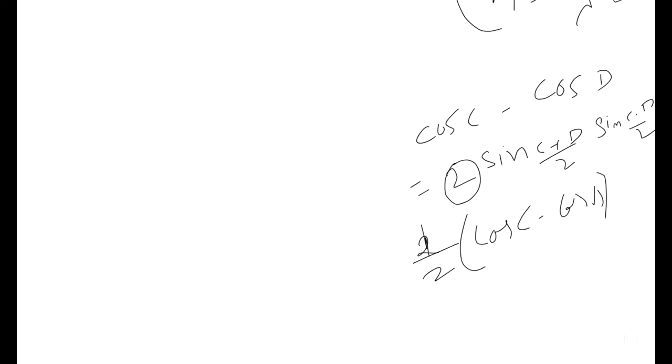We got this equation. This radial velocity is taken as two components, a cos component and a sin component. Then it is written in terms of cos and sin. Vr equals V cos theta, which I am substituting in place of Vr. So fd equals 2 times V cos theta by C times f. So fd equals 2V cos theta f by C. Here I am treating theta equal to 0, cos 0 is 1. So we get fd equal to 2V by C times ft.